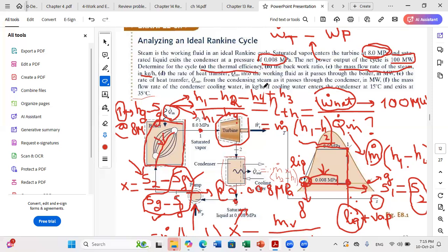Now look here, we can play with parameters. And sometimes, let's say, you need a higher output temperature for the cold water. You want to heat, for example, water up to 50 degrees, let's say. So you need to pass by a smaller flow rate. So here you can investigate, depending on your needs, what is the flow rate of water that you need and what is the temperature to reach. You can investigate what is the mass flow rate I can heat to a certain temperature.